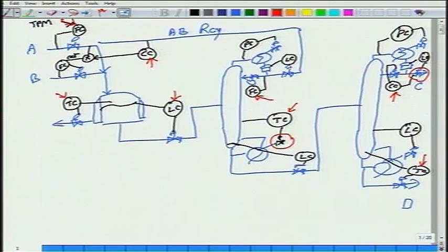When we had the throughput manipulator here, level control downstream was in the direction of process flow and level control upstream was in the reverse direction of process flow. Remember that? What was this called? This was called the radiation rule. You radiate outwards from the throughput manipulator.